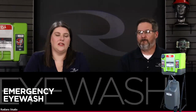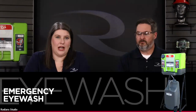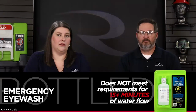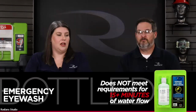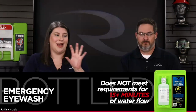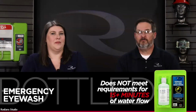Yeah, so there's something in the standard called a supplemental device, and in the industry that can be referred to as bottled eye wash, personal eye wash stations. The key thing to note here is that these do not meet the requirements for 15 plus minutes of water flow. So they're not going to give you compliance in those areas where you've determined that the hazard requires an eye wash. And like I said, if you've got a goggle that's required, you most likely are going to need an eye wash. They go hand in hand. So these exist from a supplemental standpoint.